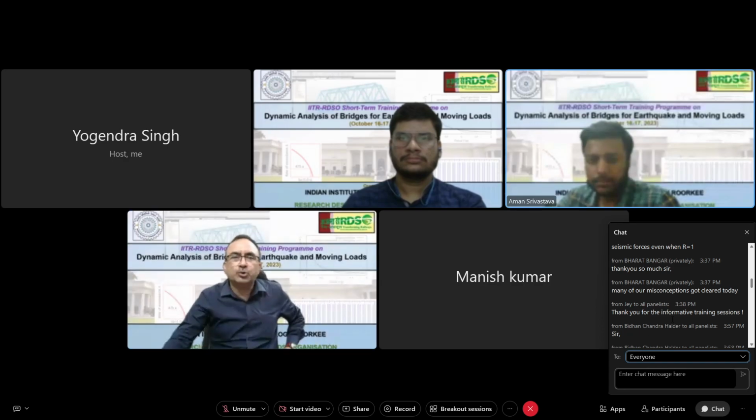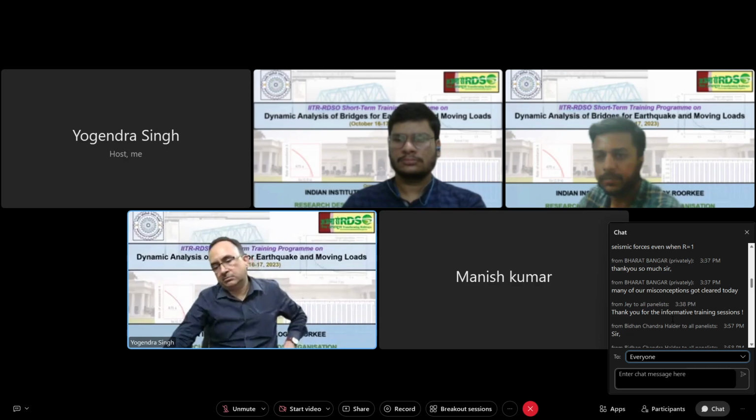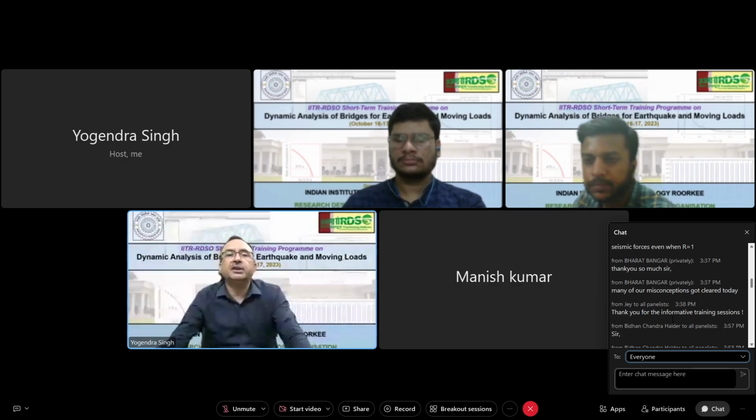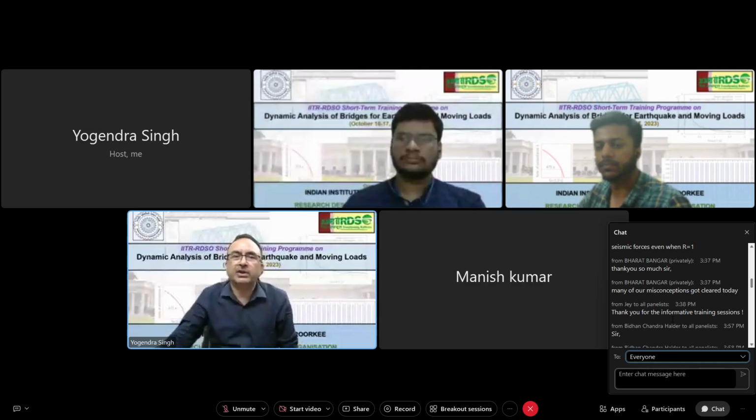Yes, but if we record any two components of a ground motion, that describes all the components. Any two orthogonal components we are recording, we can resolve those components in any other direction. So we require only two horizontal components, and of course one vertical component, to describe any ground motion. Those two components are enough, and the maximum direction will also be obtained from those two components only, that is, in which direction the maximum ordinate will occur.